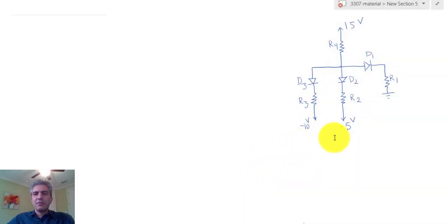Hello everyone, in this video I'm going to discuss another multi-diode circuit, hopefully to guide you through the process of dealing with more than one diode in a circuit. As I explained, if you want to blindly approach the problem, you actually have to assume that each one of the diodes in a circuit could be on or off, and that could be quite cumbersome, especially if the number of the diodes increases. In this case, for example, you have to consider 6 different circuits before you can actually invalidate the wrong assumptions and find which one of the assumptions is actually valid.